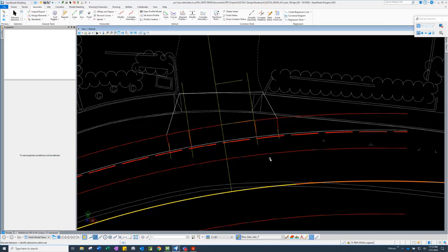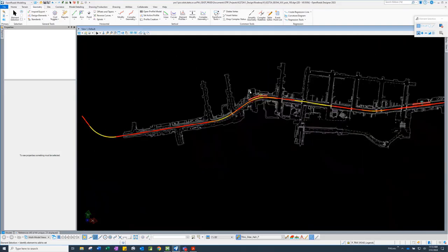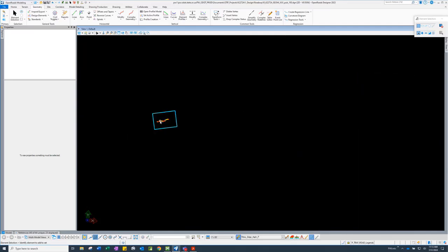And then the other command that you were using to draw all of these lines was actually under the lines command, and it's a line between points. So if we look at that, it's line between points. Just wanted to focus on the commands. So let's see, your next step now, unless there's other questions about the driveway, is to continue with the curb return that you had started. Correct. And the bulb out there. Okay.